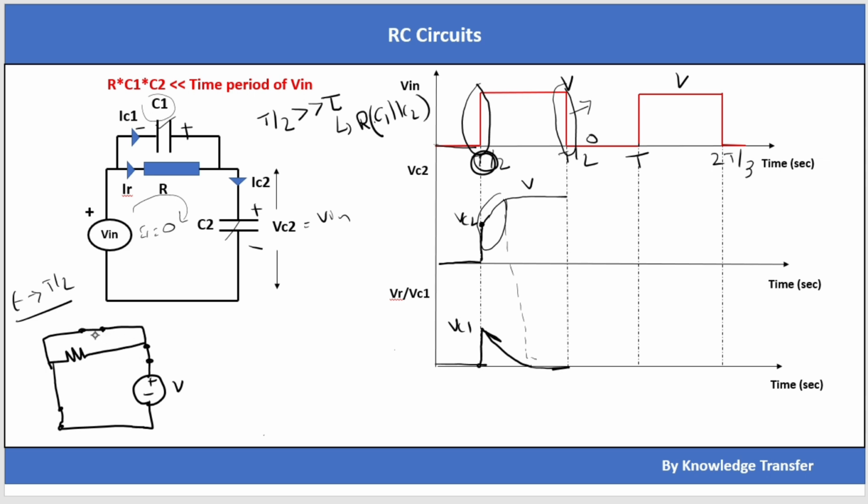Because there is a capacitor here which is again short circuit, at t equal to 0 itself we can say that an infinite amount of current is again flowing through capacitors C2 and C1, because the current will take the least resistance path. Because of this infinite current, the charge inside capacitor C2 will equally distribute to C1 also. So how will it get distributed?